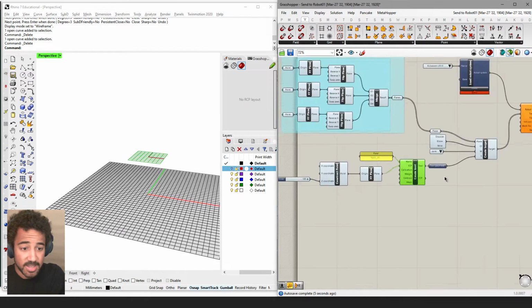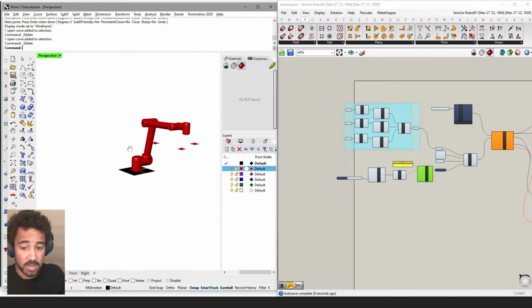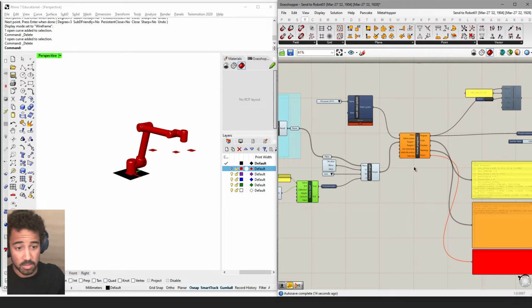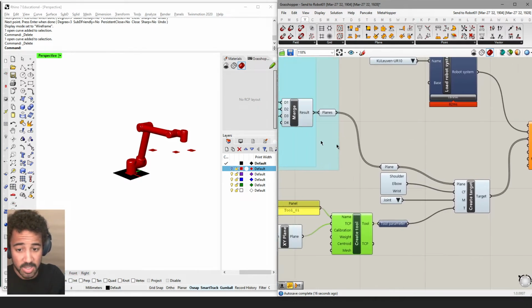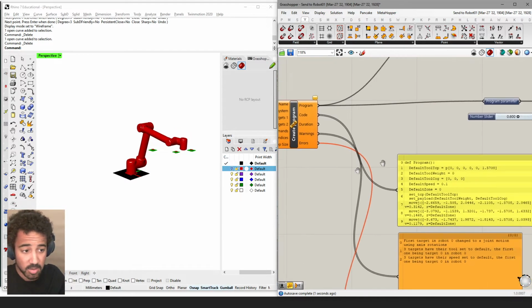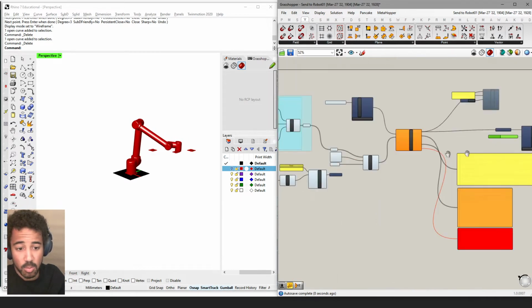What this does then is to make sure that this robot, instead of before, the robot simply had the flange basically touch each of these waypoints that we defined. So let me show you what it did before. I will disconnect the tool, and you can see that these three planes that we defined as our robot waypoints, the robot basically touches them directly with its flange because there was no offset.